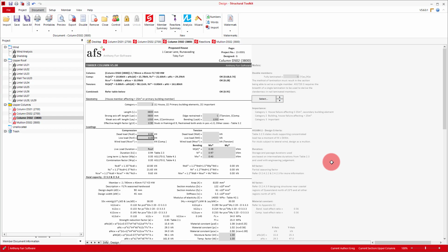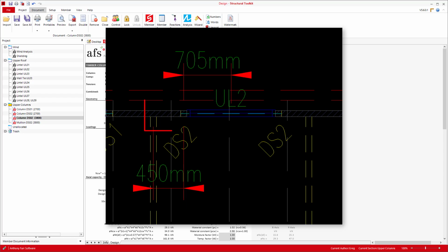An experienced engineer may have already anticipated something like this, and so may not have needed to go through all these additional steps. But for the purpose of this video, it should help showcase the iterative nature of engineering. Now, usually you would also have to design some studs to go between our column and the internal return walls at the edges of the stair void. However, as the distance is only 450 millimeters, we won't need to add an additional stud in between.